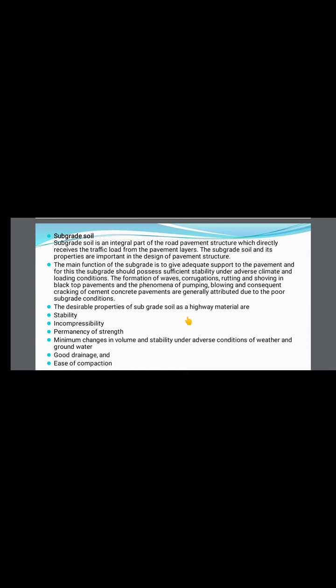In the soil particles there will be pores. If you take a loose soil, it is less dense. In between the particles there are pores, and those pores are occupied by water, so the volume will be increased. When the load is applied upon that, what happens? The water from these pores gets expelled, so that it will get compressed.